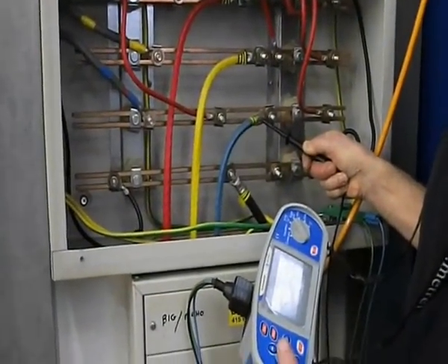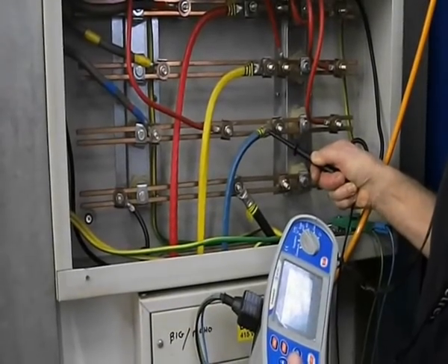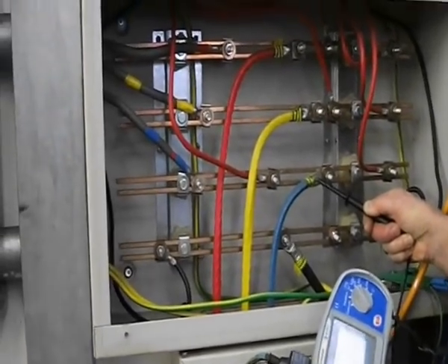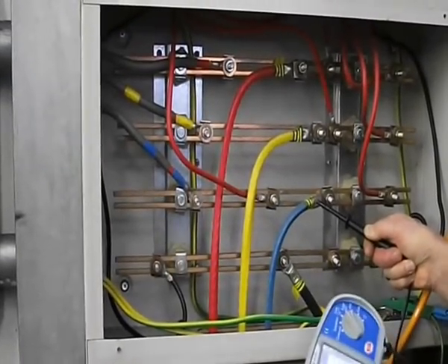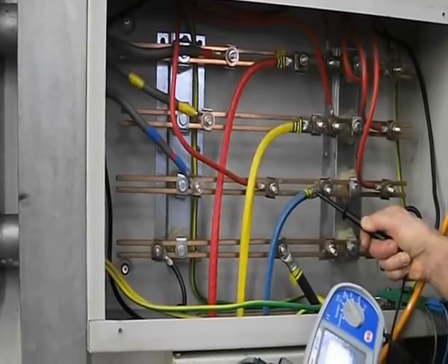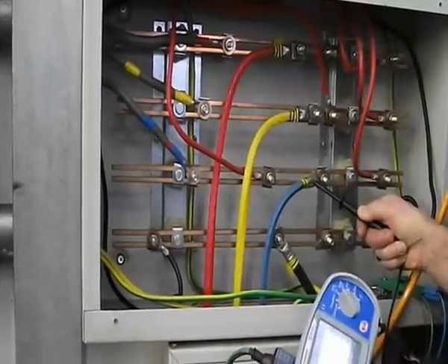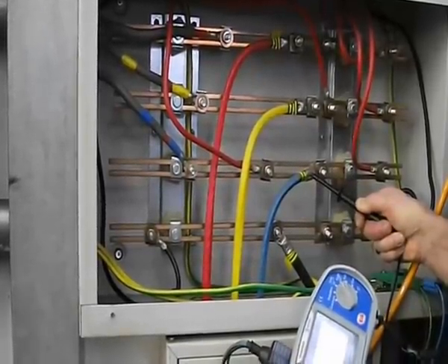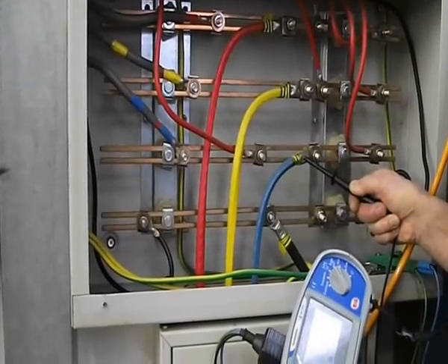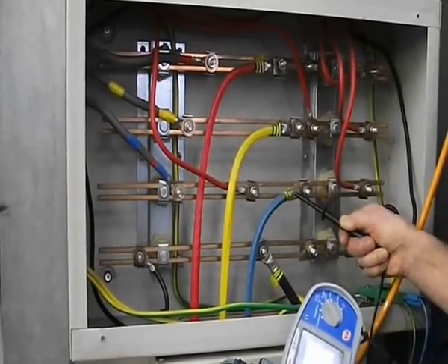What's being conducted here is another test of line output impedance, this time with a meter tester, and there's some discrepancy between the readings because we now have 0.13 at a location which is slightly remote from the mains. But discrepancies such as this are likely where you've got very low values of line-earth loop impedance. Contact resistance can make a big difference in percentage terms.